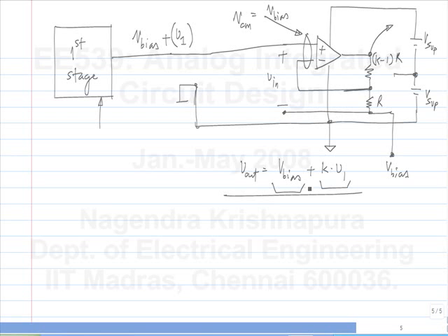So the reason I am going through this whole thing is that when you have to simulate circuits and so on, there will be some confusion about what the ground is and things like that. When you see a classic op amp circuit, this is all you see. Or let's say we take an inverting amplifier. This is all that's there. Now this schematic will more or less work if you do have dual supplies. Then fine, this is ground and that is ground and everything works. But if you have a single supply, what do you do? There is nothing fundamentally complicated here. It's just a matter of adjusting the bias voltages.